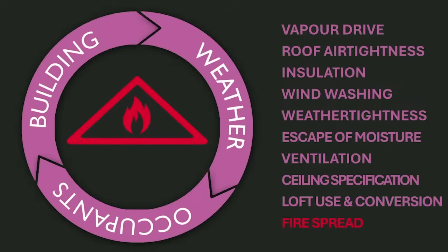B3 Clause 4 also requires measures to be taken to limit the unseen spread of fire and smoke within concealed spaces. And Sections 8 and 9 of ADB1, and 9 and 10 of ADB2, detail the provisions that should be made to ensure cavities and openings are adequately fire stopped, for example with cavity barriers or other proprietary systems. Externally, Requirement B4 requires the walls and roof to resist fire spread over the element and between buildings.